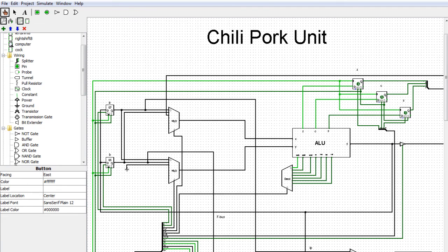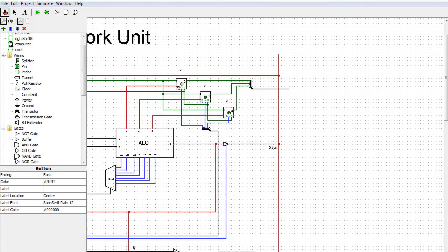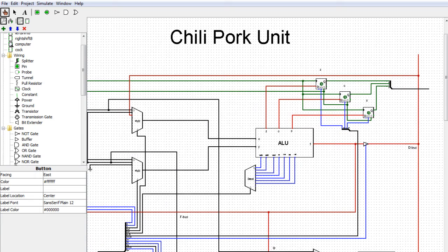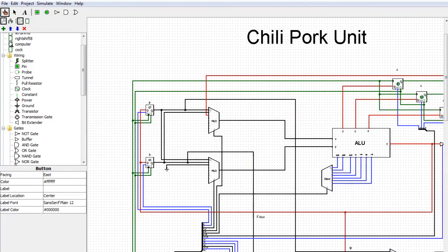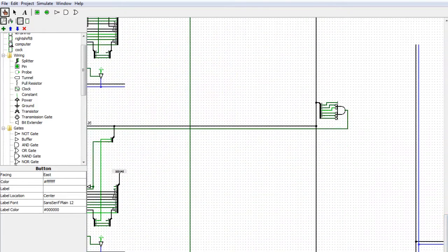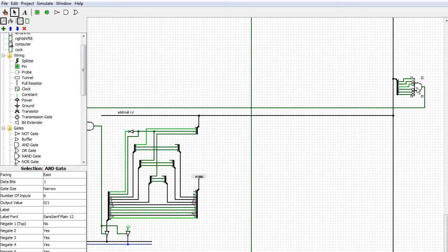Alright, so if I clock it low, it's going to load this into here. And, okay, so here's the problem. First of all, this is not even connected. Why is this not being driven? Because it should be driven. A whole bunch of things aren't being driven, which means, okay, I got it. I forgot to set the decoder on the instruction.